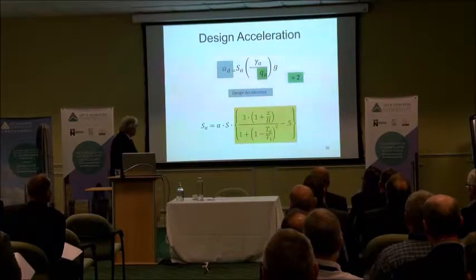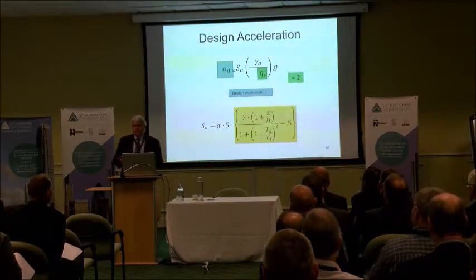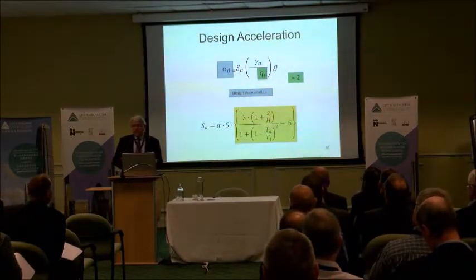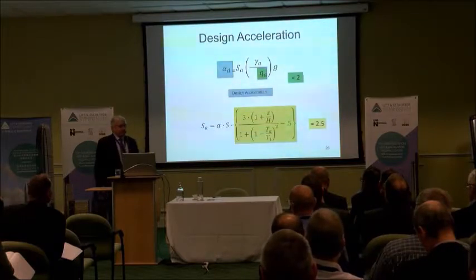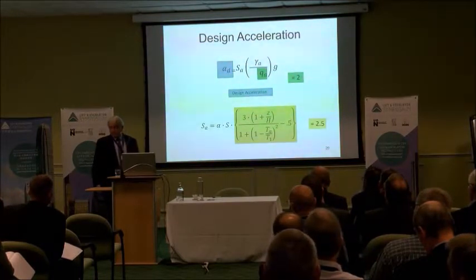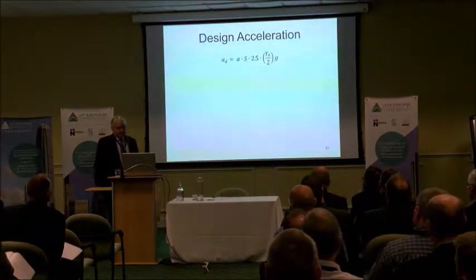The other thing is this block of this equation basically has to do with when you have a situation where the lift machine is very heavy at the top of the shaft, and so it enters into the oscillation frequency of the buildings. But in most applications, this isn't really a factor, and so this reduces to 2.5. So now it becomes quite a bit simpler formula to look at, and this is what you end up with